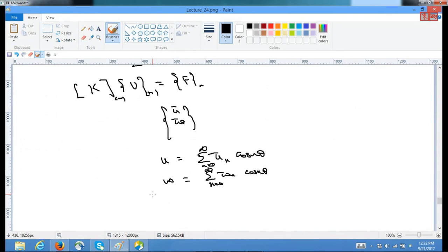Sometimes it is really worth dealing with non-axisymmetric loads in this manner, because the computation becomes too expensive if you do it in 3D. Here, you may be solving 4 or 5 combinations, each one in a 2D sense, and superposing these 4 or 5 problems, because not all n will be active, or not all projections would be active for given loading conditions.